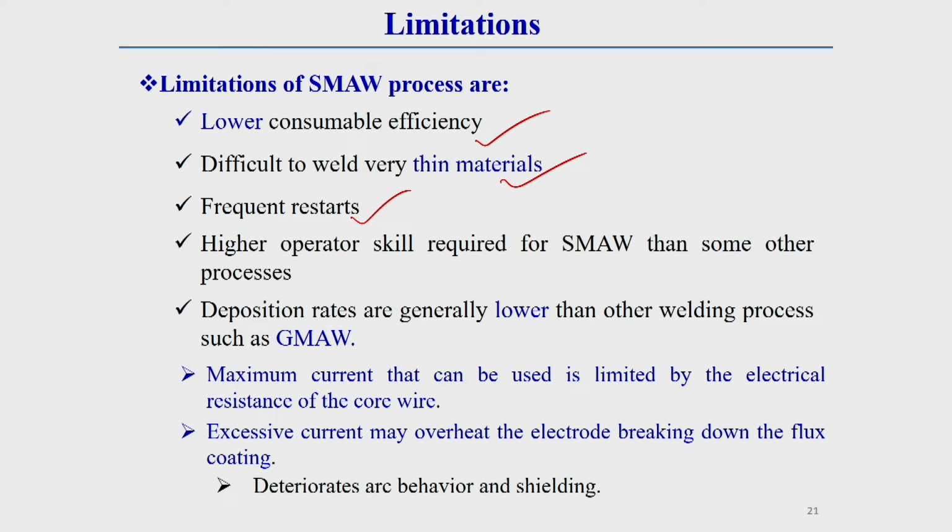Why? That you should know, because here one thing you should keep in mind, we cannot increase the current through the electrode as much as possible. Why? Because this electrode has a resistance. If the current flow is more through this electrode, there is a chance of overheating of this electrode. Due to this overheating, there is a chance of deterioration of the flux cover.